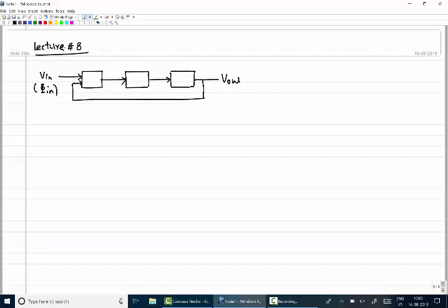Output is voltage signal V out, but we are looking for phase at the output. And we have phase detector, loop filter, and oscillator. So this is the block. What we have seen is a typical PLL: type 1, order 2, type 2 and order 2. This is something which we have seen so far.